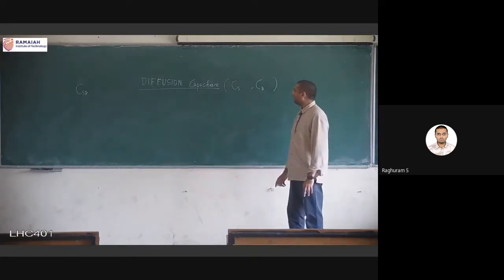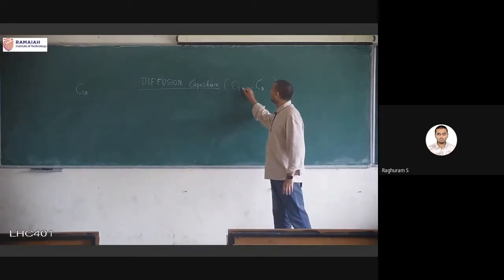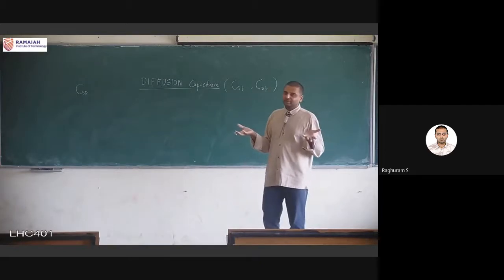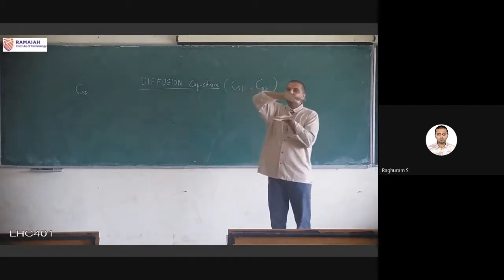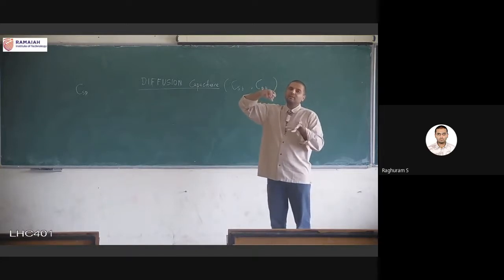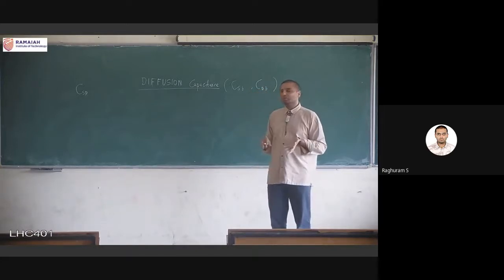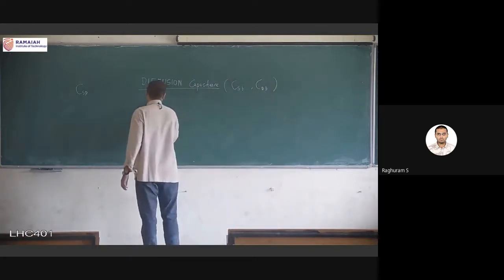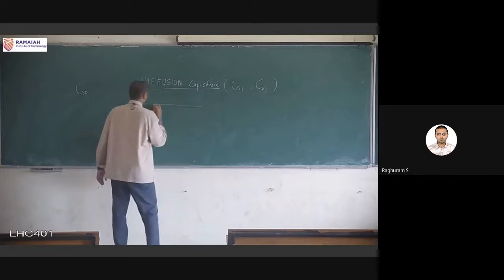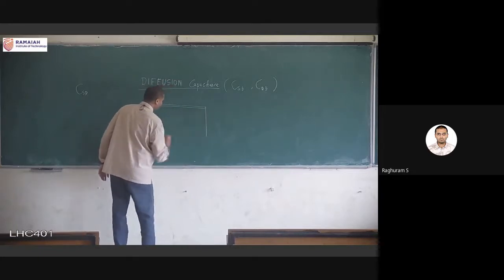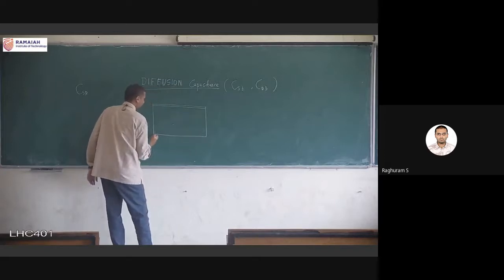If you have not guessed by now, that is the bulk terminal. We have the source and the drain, and on top they are covered by the insulation and they have a metal contact. Below is where the capacitance comes into the picture. So we will see in this cross-sectional diagram again what the capacitance actually is and what the reason is for this parasitic capacitance.